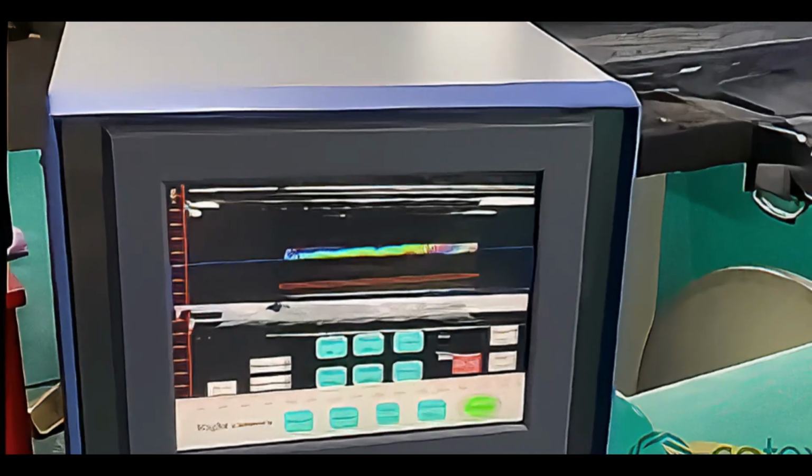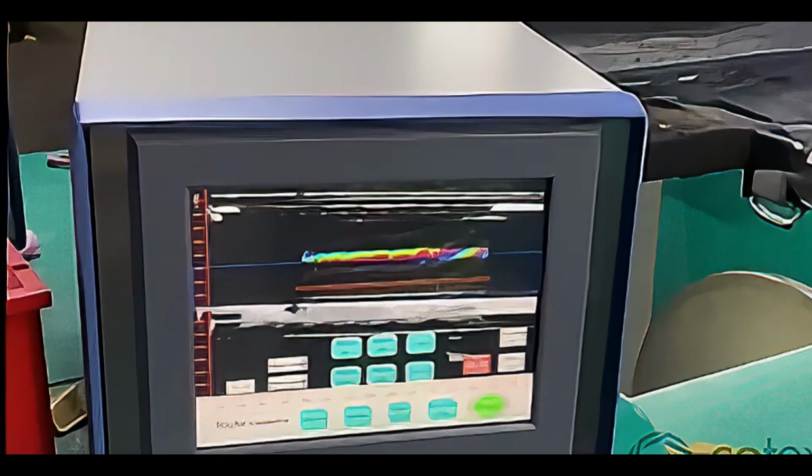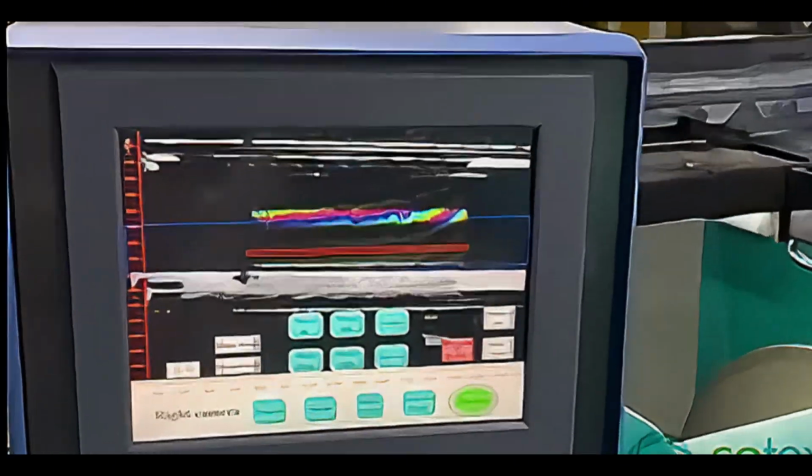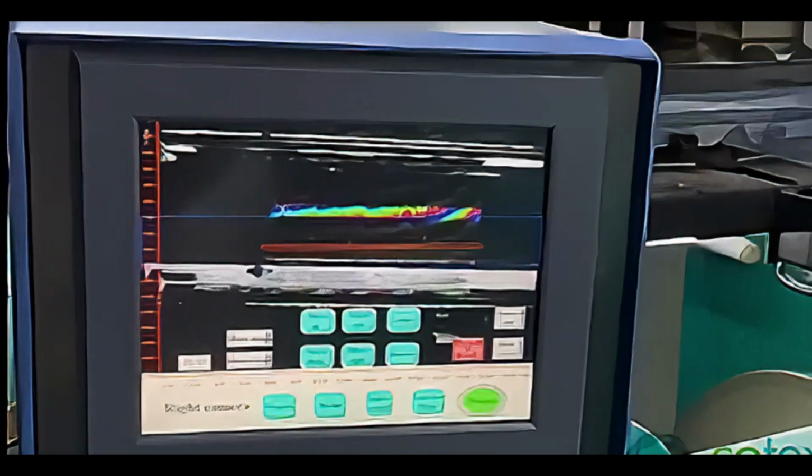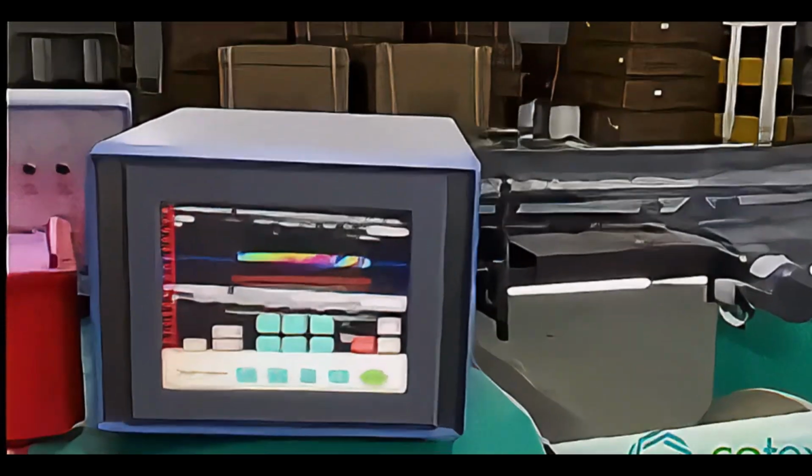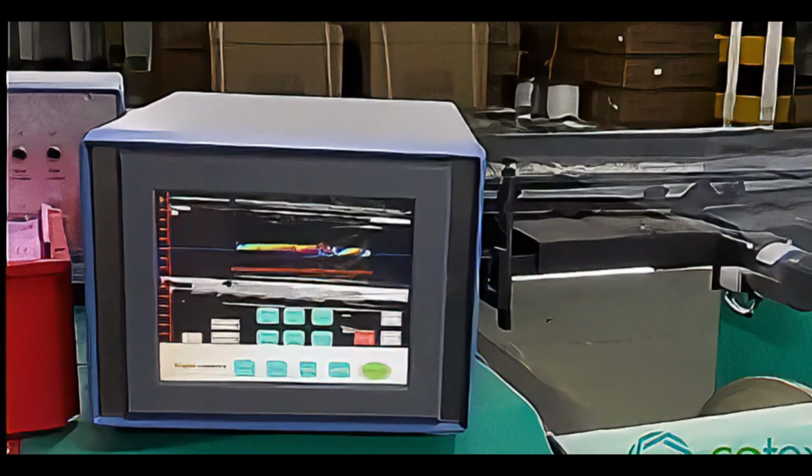Now, slowly rotate. Try to make the color distribution in the left, middle and right parts of the color bar as even as possible. After completing this action, gently tighten the screws that were just loosened. But it should be noted that when tightening the screws, it is easy to break the adjusted color distribution, causing the color bars to become blurred. So remember to tighten it lightly so as not to affect the color bar as much as possible. Tighten the screw lightly while checking the clarity of the color bar at all times, to ensure that there is no problem before tightening.